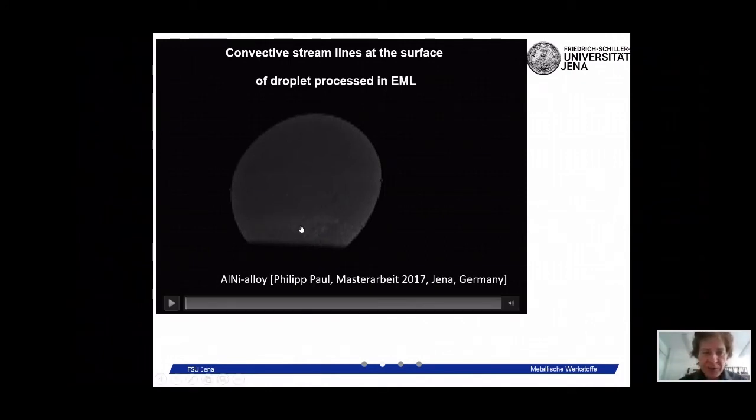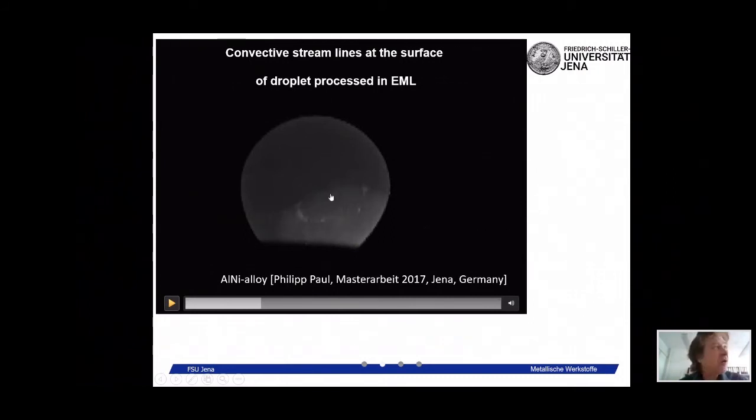But anyway, it was natural. We did not make something special. We only watched this movie, and I selected this. We have several hundreds of movies, and I selected this movie in order to show that these oxides show us complicated curls on the surface of this droplet. You can see, and then at some point we got bright propagation of this front, because in this part we have the release of latent heat, and latent heat makes this part brighter than the dark part related to the remaining undercooled liquid.